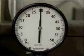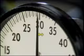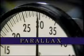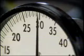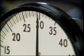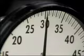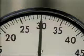Many indicating instruments use a pointer and a scale to indicate a measured value. When there's a gap between the pointer and the scale, an optical illusion called parallax has to be taken into account when the instrument is read. For example, when this pressure gauge is viewed from the right of center, the pointer seems to indicate 29.5 pounds per square inch. But when the gauge is viewed from the left of center, the pointer seems to indicate 30.5 pounds per square inch. When viewed straight on, we can see that the pointer is actually indicating a value of 30